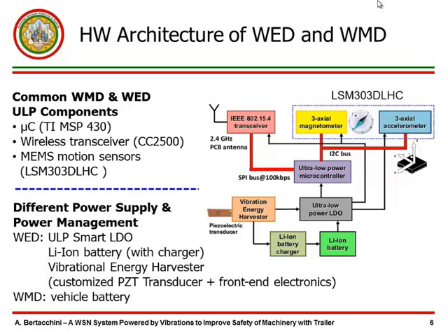If yes, okay, no problem. If no, the ultra-low power switch connects the battery directly with the node to guarantee the correct operation. If there is a surplus of energy, of course, this can be used to recharge the battery through the battery charger.